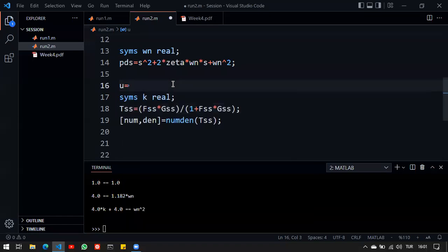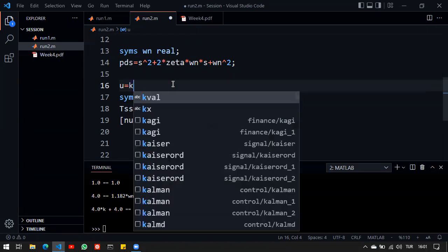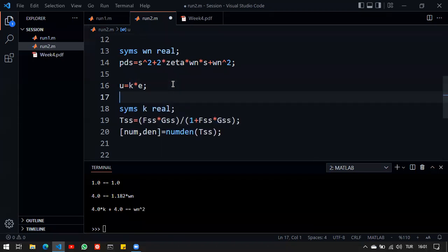And using a P-type controller, what I'm actually doing is I'm choosing a gain, since I have a feedback loop, and in this feedback loop, there's a certain difference between the reference and the output called the error. And I'm taking a proportional part of this error and applying it to the system. So what if, for example, I can also use another piece of data here, namely the derivative of the error.